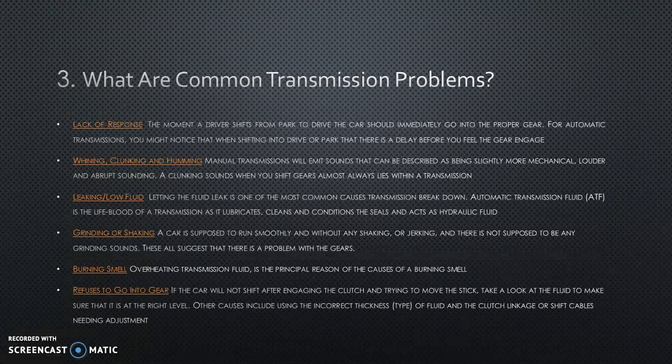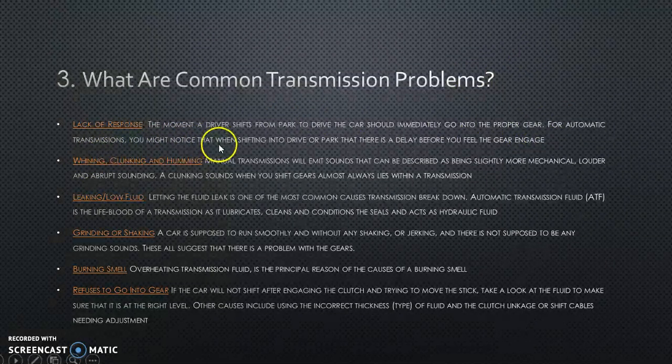Number 3, what are common transmission problems? Lack of response. The moment a driver shifts from park to drive, the car should immediately go into proper gear. For automatic transmission, you might notice that when shifting into drive or park, there is a delay before you feel the gear engage.